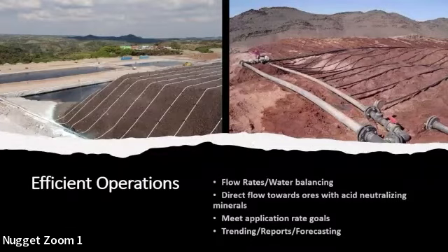With this setup, the flex wall, you can also do unsaturated hydraulic conductivity measurements, essentially irrigating on the top of the cell at a particular rate, and then you can consolidate to look at what the solution content would be in that material under different flow rates at particular depths in the heap leach pad.